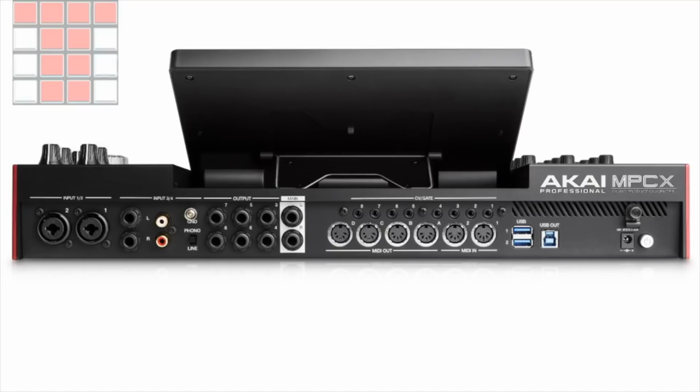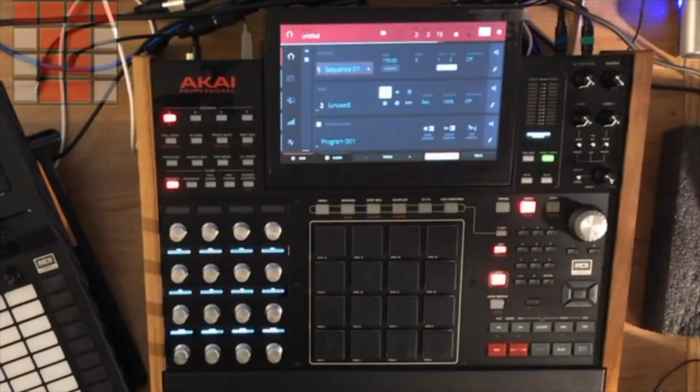If you're using the RCA phono inputs and you're recording from a turntable, you want to switch that switch to phono, and that will record any audio source that you've got connected to the phono connection, which would usually be a turntable. If you're using the 1/4 inch vertically orientated ports, that is inputs 3 and 4, but that's the line connection. If you've got a CD player or another synth or another line level source, you can connect that there. So let's return back to the top panel.